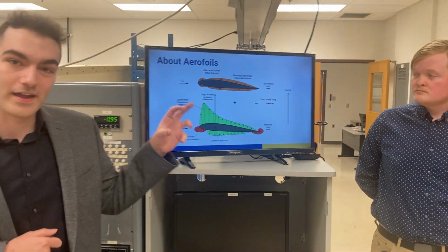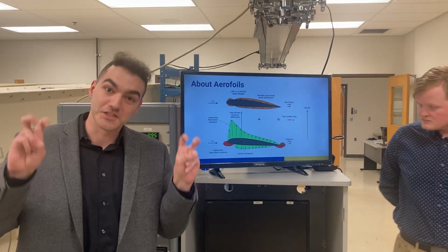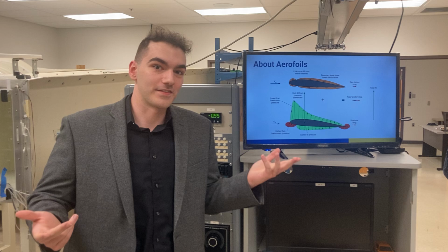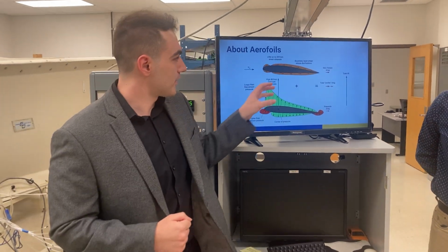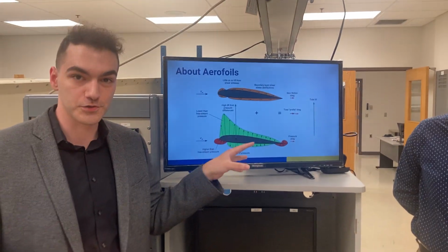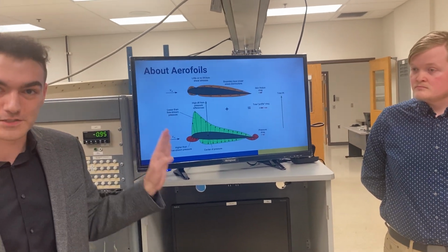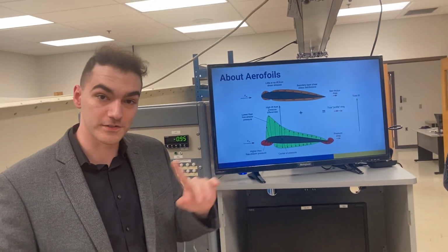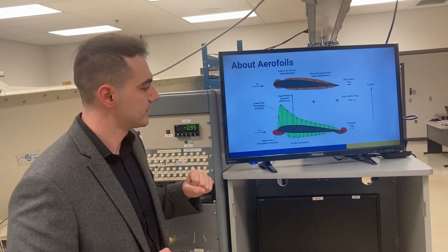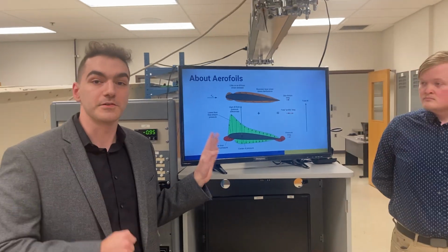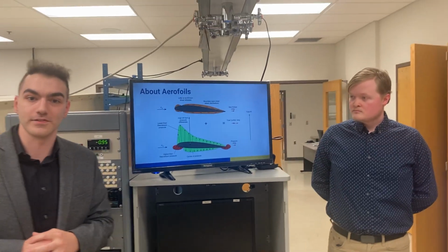The air has a tendency to stick to objects. It has viscosity, much like oil, water, anything of that sort would. That produces drag, from shear stresses, disrupted flow, and skin friction drag. The frontal profile area, that's the projected area, which we'll talk more about as we get to our testing methodology, also generates drag, with actual friction at the stagnation point at the front where velocity is 0.